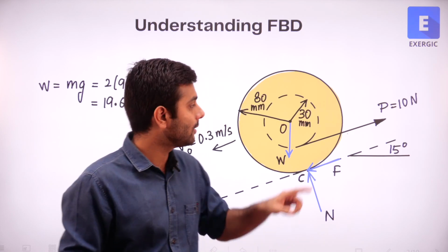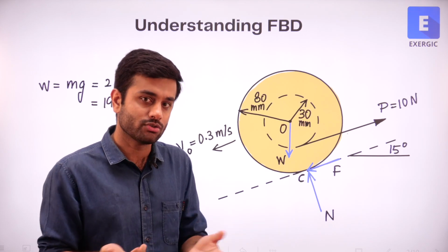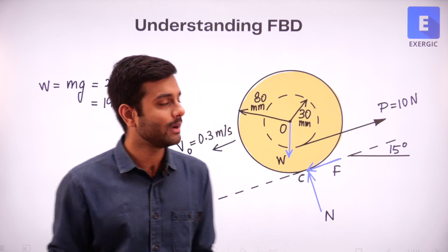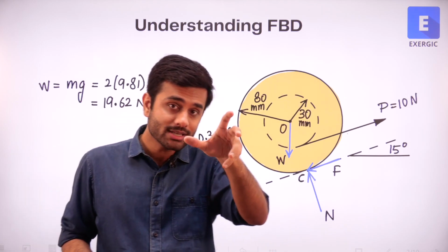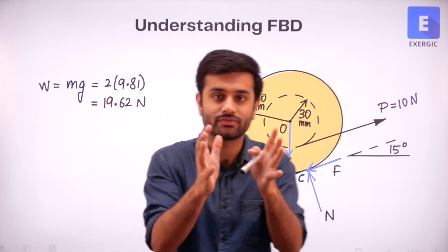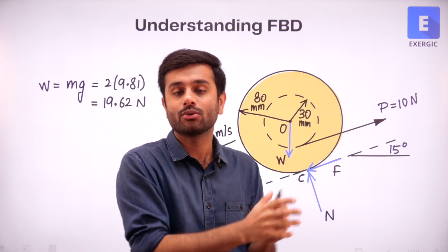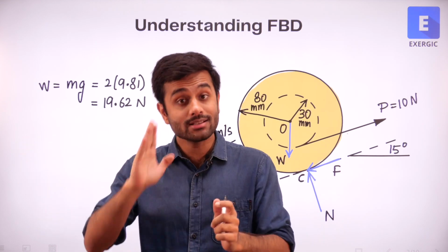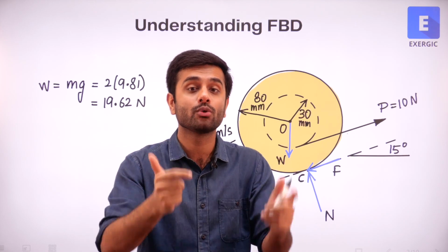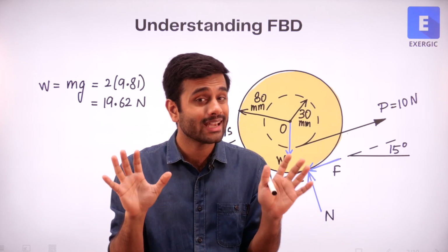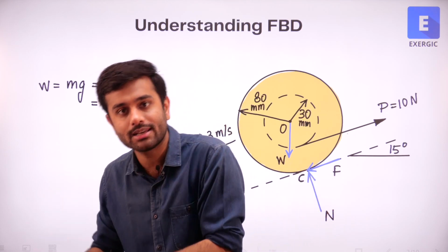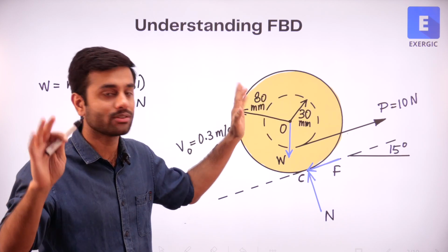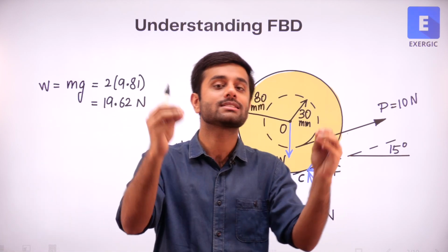we do it about the center. It is very much logical also, because rolling is a combination of translation and rotation. Translation anyway is going to be complete translation, but rotation is about the center. When you combine both of them, the net vector sum gives you the dynamics of pure rolling, something that we have already discussed. So when we are doing a complete pure rolling analysis by breaking it down into translation and rotation, the rotation component has to be about O. You cannot take the rotation about this point, you will get the wrong answer for sure.